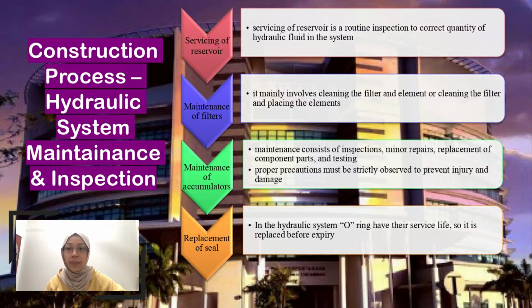Point number 3. Maintenance consists of inspection, replacement of component parts, and testing. Proper precautions must be strictly observed to prevent injury and damage. Point number 4. In the hydraulic system, O-rings have their service life, so they are replaced before expiry.